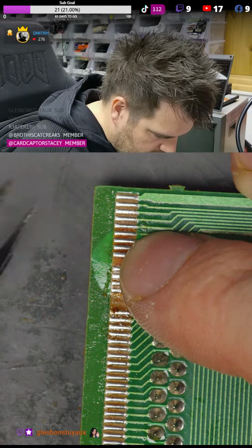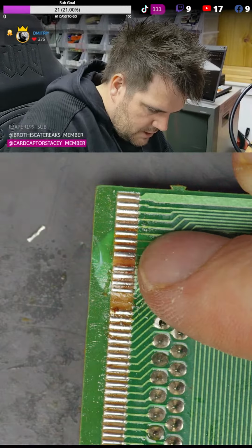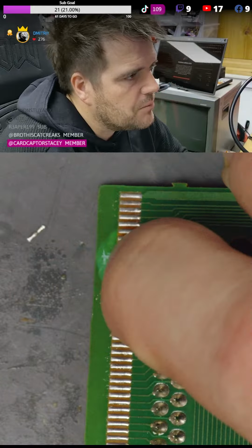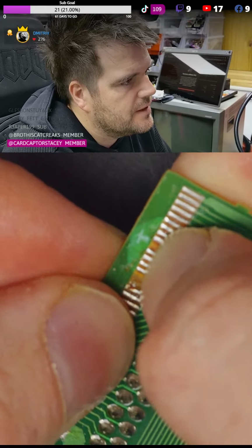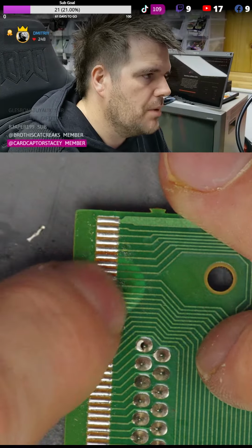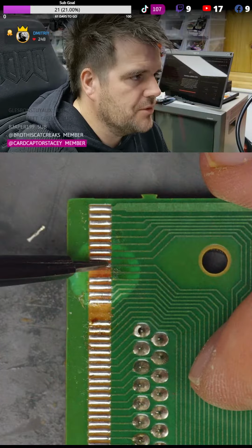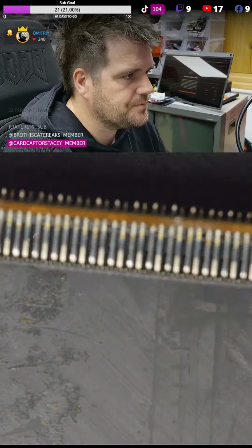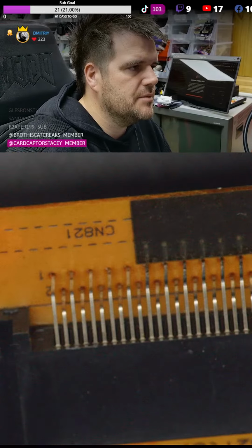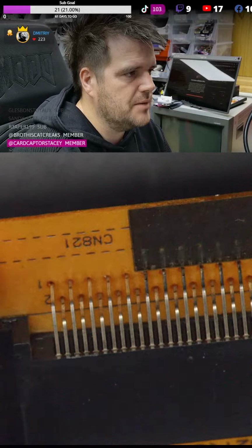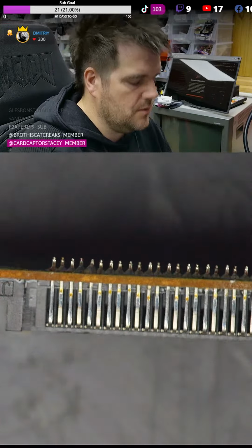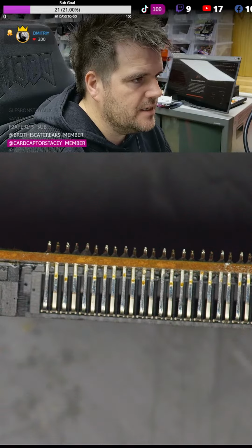If this happens, it looks a bit brutal, but you can usually stab through the board to get between the layers and then push the air out, if you will. That's what popcorning is, when it's normally from too much heat or moisture in the board. Because this is a paper PCB, these bright orange PCBs are, for the most part, just compressed paper. You might as well think of them as paper with a bit of bonding glue in. So fluid can get inside here and penetrate very easily.